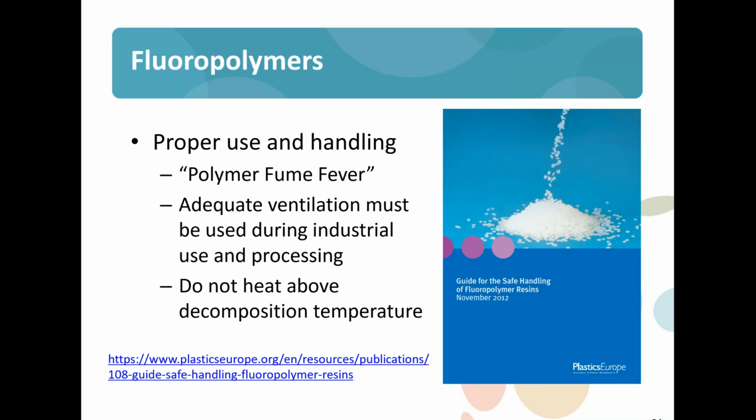When you put a nonstick pan on top of a stovetop and it doesn't have the right things in it, or it's overheated to the point of actually starting to decompose not only the food in the pan, but the pan itself, the polymer can degrade and form volatile substances that can be harmful. And birds are particularly susceptible to inhalation toxicity. So there have been lots of cases where fluoropolymers that have been heated well beyond their foreseeable use condition, thermally degraded because the heat was left on, that bad things happen.